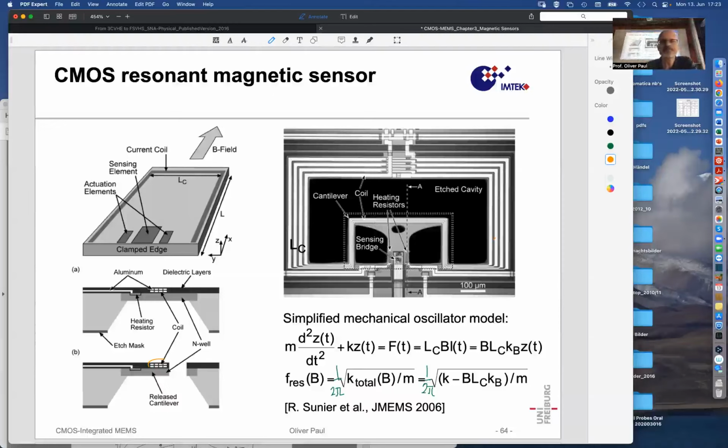Yeah, and that's this, and the structure is, as I said, realized by some reactive ion etching and silicon etching from the back and from the front. And so the mechanical model of this structure is that the structure wants to work against its own deflection by a mechanical spring constant. It wants to be in the middle. Any deflection is bad, and so the middle is best. That's described by this term. So that's the mechanical spring.